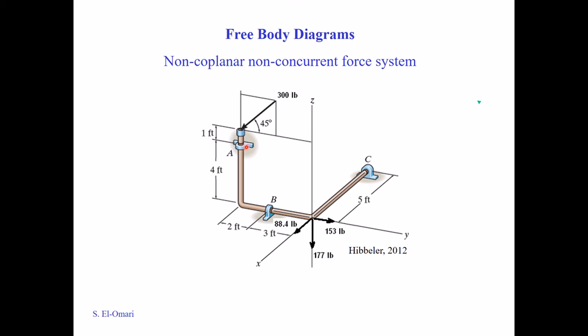So back to this support. Again, you look at the support and think, let's look at the x-axis. Will it prevent it from moving along this axis? Yes, it will prevent it. Then you place AX. Will it prevent it from moving along the y-axis? Yes, it will. Then you place AY. Will it prevent it from moving along the z-axis?